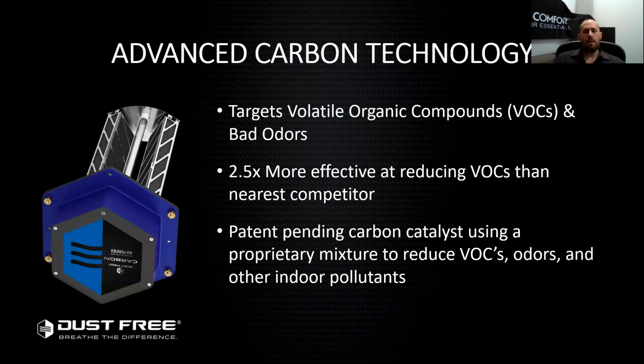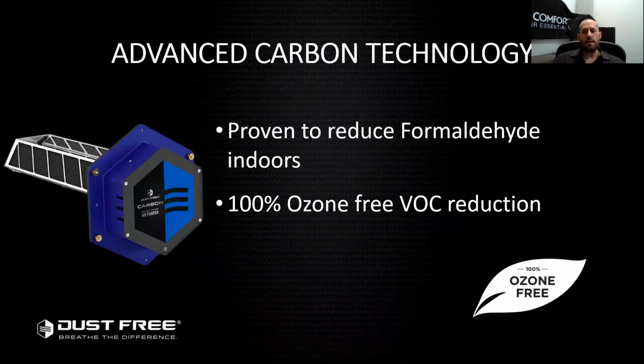So this carbon unit has a UV light that does clean the coil, while the carbon does a great job with odors, formaldehyde, and VOCs. The nice thing about this technology is that it is 100% ozone free. So we use this in a lot of applications where we cannot add anything to the space, or for people that are chemically sensitive.